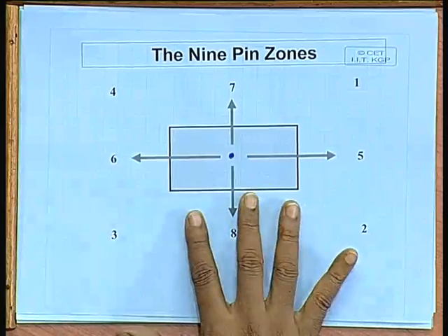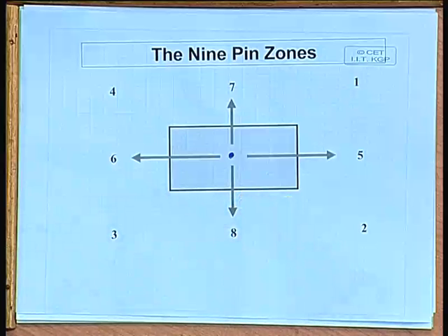So does that mean that we are going for full custom design? Yeah, in this method we are assuming full custom design. The pin definitions are not yet fixed. Internally we can make those changes, because if that ordering is fixed, then you cannot do much by playing around, because once one of the rectangles is fixed, the others get severely constrained. You are right. What was the sequence you said, like first you minimize the area, then you map it to different zones.